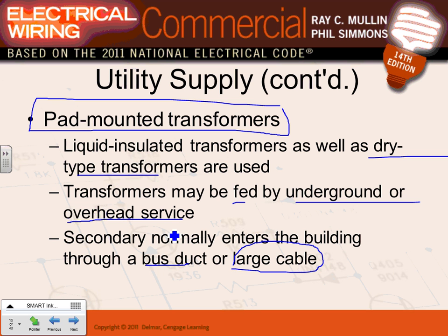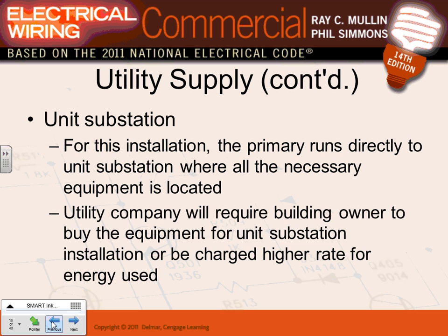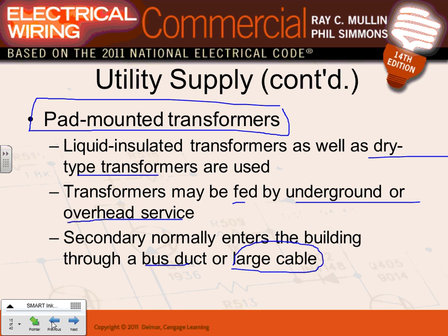So this is what we have in our commercial building. We have a pad mount transformer. We went underground with conduits and we fed feeders into that meter. So the bus duct, basically a bus. Bus duct is manufactured, sandwiched copper bars or aluminum bars in close proximity to each other, phase A, B, C, and a neutral, encased in metal, and brought to your building.